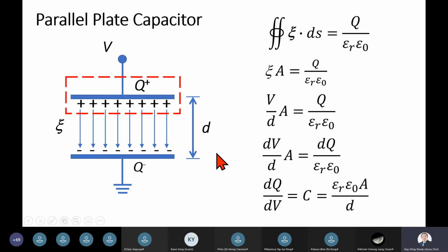You can apply Gauss's law to other kinds of situations. In fact, we did that earlier to the PN junction, in case you didn't realize it, in the form of the Poisson equation. The Poisson equation is actually the differential form of Gauss's law, as you can easily see. Now, the concept of the parallel plate capacitor is useful because later, through the discussion of the PN junction capacitance, you will realize that its behavior is quite similar to the parallel plate capacitor.